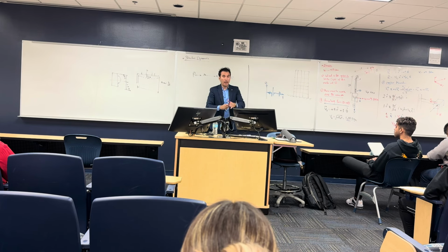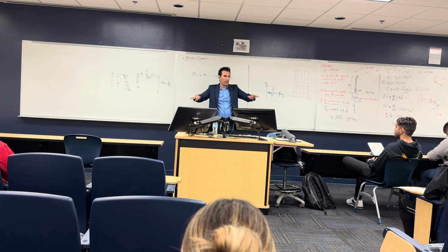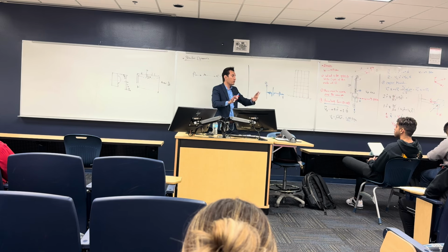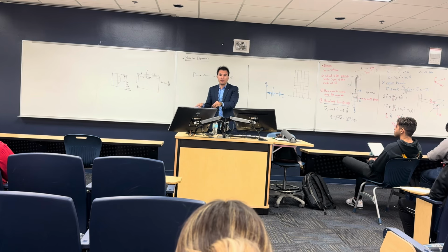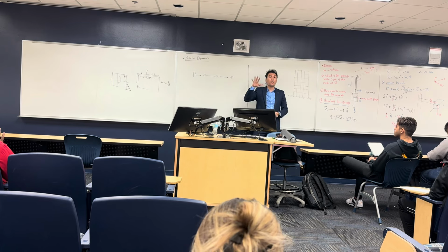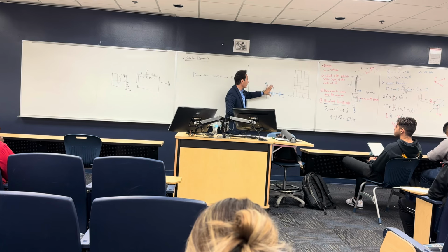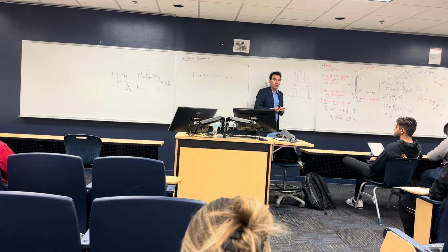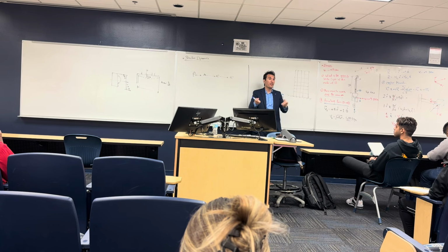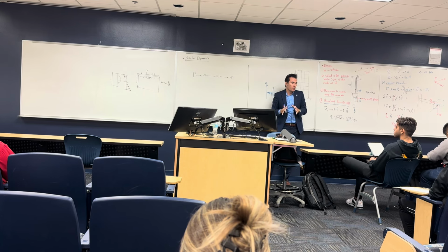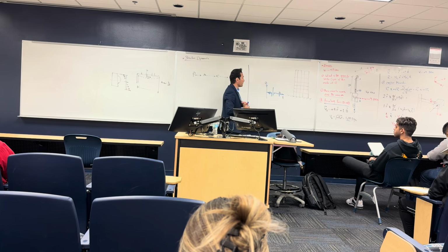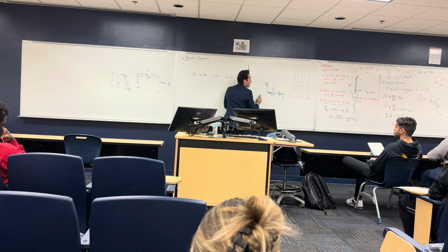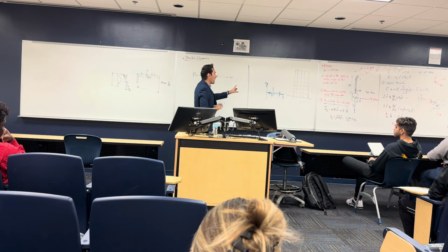And actually, every building, let's say Miami got hit with an earthquake, and this is really happening. But let's talk about Los Angeles, LA, getting hit with an earthquake. Every building has a different mass. However, the earthquake is the same, but every building is going to absorb a different force from this earthquake, depending on the mass. If your mass is big, you're going to absorb more force. If your mass is small, you're going to absorb less force. Okay, so we call this a_g, the earthquake acceleration.